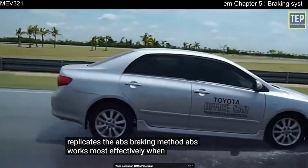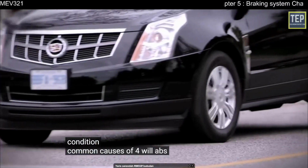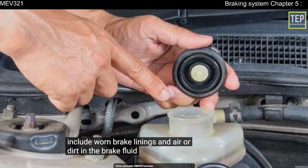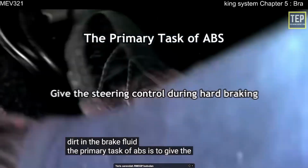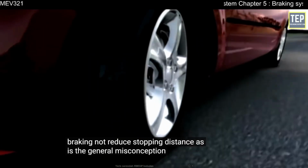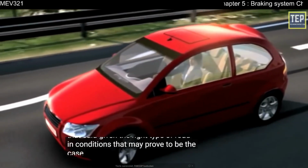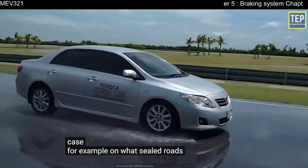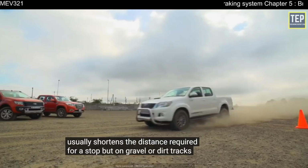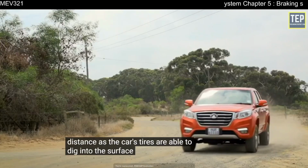ABS works most effectively when the tires are properly inflated and in good condition. Common causes of four-wheel ABS malfunctions include worn brake linings and air or dirt in the brake fluid. The primary task of ABS is to give the driver steering control during hard braking, not reduce stopping distance, as is the general misconception. That said, given the right type of road and conditions, that may prove to be the case. For example, on wet sealed roads ABS usually shortens the distance required for a stop, but on gravel or dirt tracks, skidding may actually decrease stopping distance as the car's tires are able to dig into the surface.